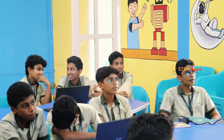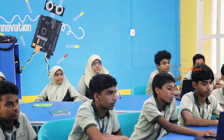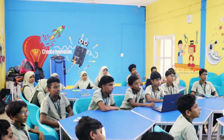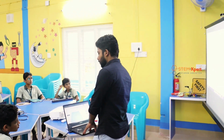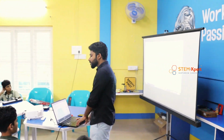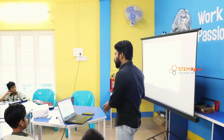Okay, so this will be the work plane. Here we are adding the objects, right? Yes. And these are the shapes, basic shapes we can find. And here there are some tools like grouping, align, mirror. So like these kind of tools are there, and on the left side you can find different perspectives. Okay, so you can zoom in, zoom out, fit view is there, and home view. So whenever you want to go to the first view like this, you can click on to the home view. It will take you to the initial perspective. Okay, and you can use this cube to rotate, and you can view it in any angle.